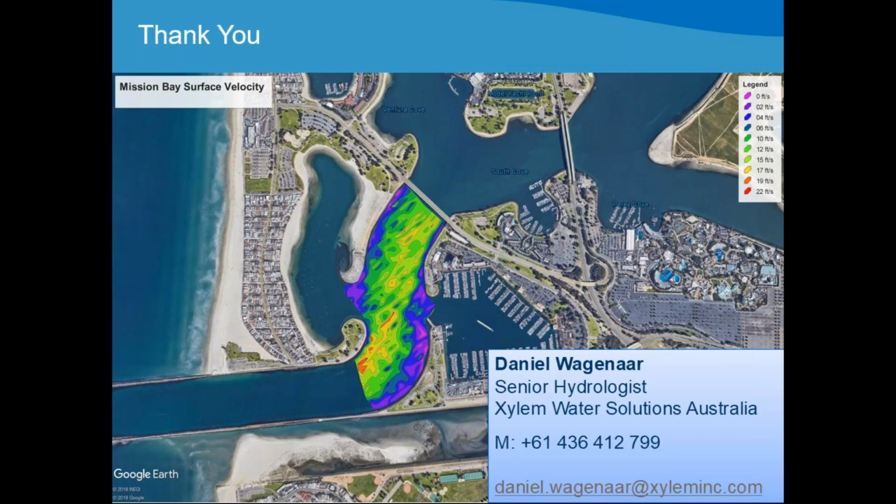Okay, thank you, Daniel. Next, if we have greater water velocity, say greater than 4 meters per second, would the 16 centimeter blanking distance be sufficient, or should we set a larger blanking distance based on observations at that time?